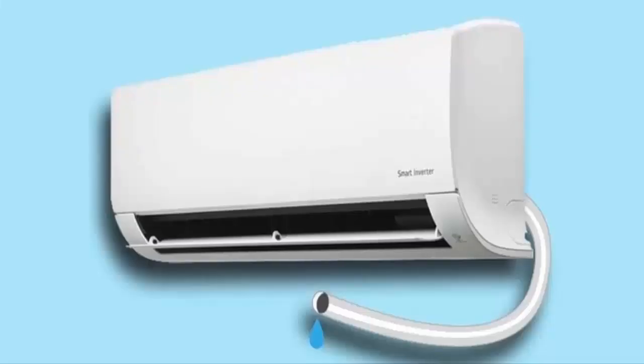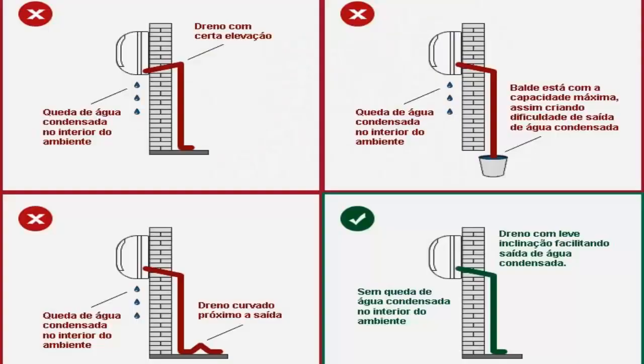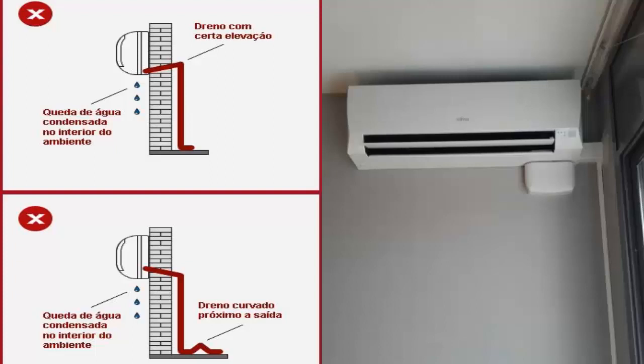G. Do not ignore the correct location for drainage hoses for condensate water generated in the evaporator. Solution. Observe recommendations for hose placement. Avoid using drainage pumps in the evaporator whenever possible.